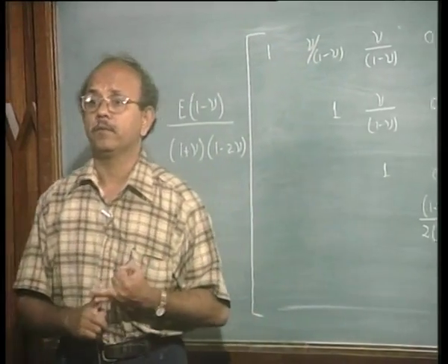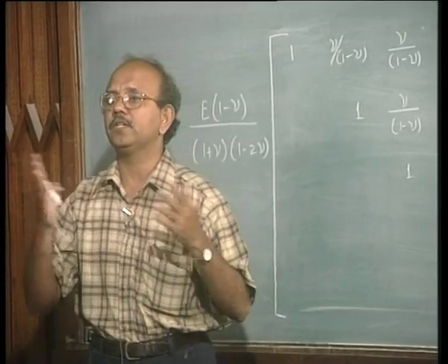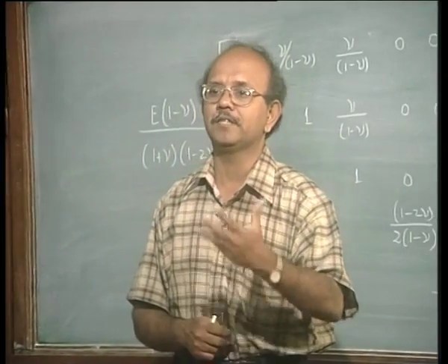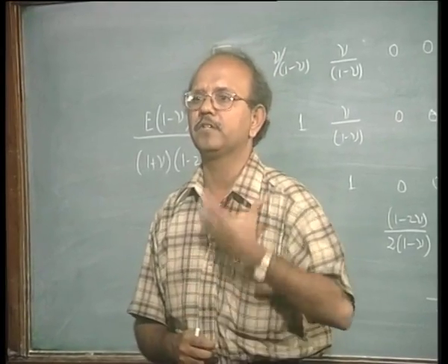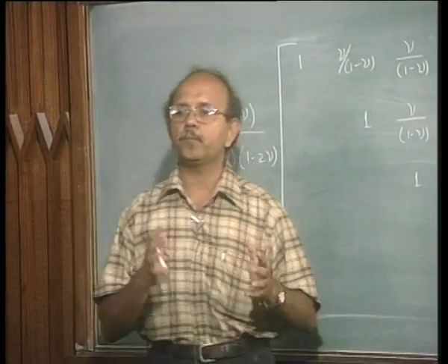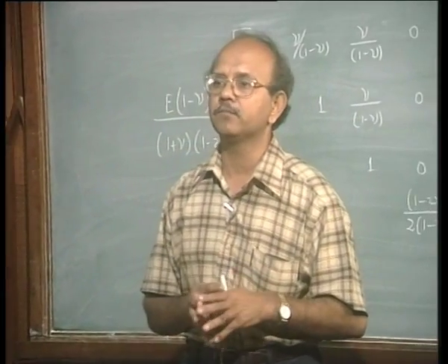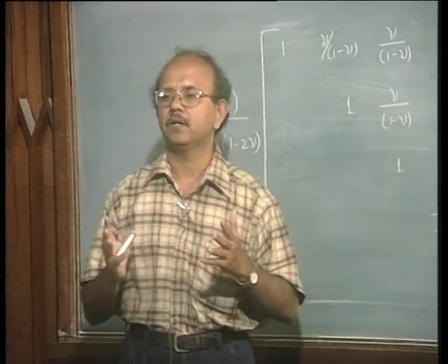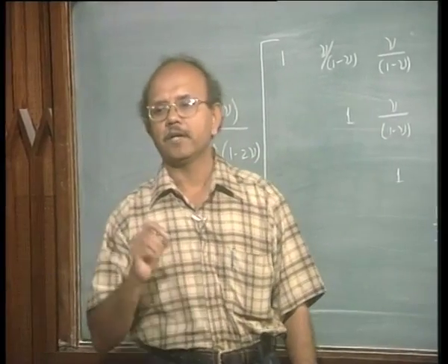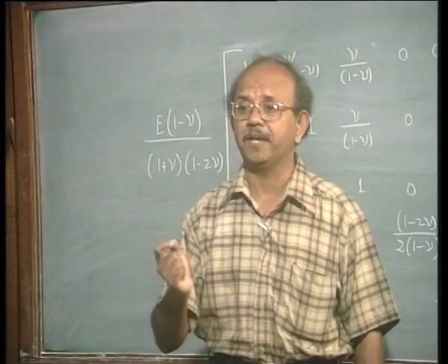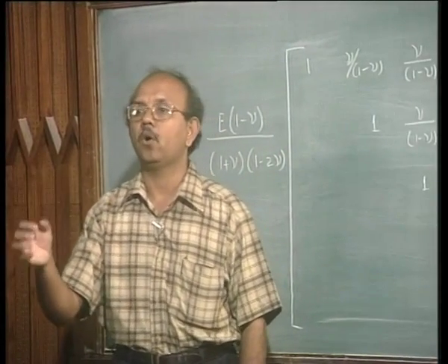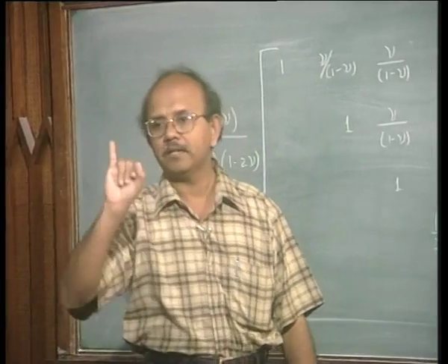That is number one. Number two, when you go to 3D, the problem size also increases tremendously. The problem size is not going to be small. So when the problem size increases, your computer space increases, time to solve increases, all sorts of complications are there. In fact, I should add one more thing. Post processing, or looking at the result, becomes very difficult when you go to 3D rather than 2D. You may not understand it that easily, and the visualization becomes slightly difficult, whereas in 2D, all these things may not be there. At the same time, a word of caution: you should not rush to 2D or plane strain, plane stress, axisymmetric instead of solid all the time. So overall that is the first thing.